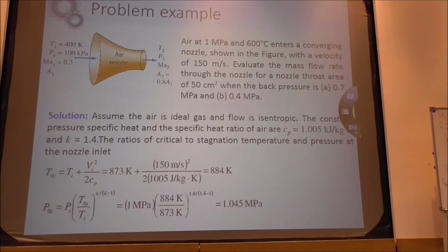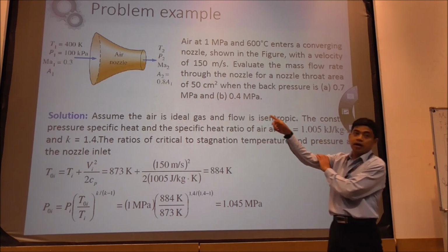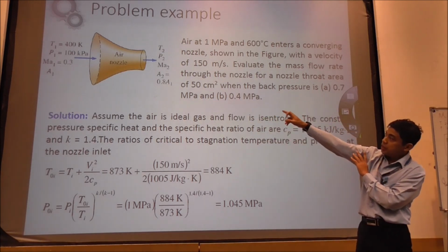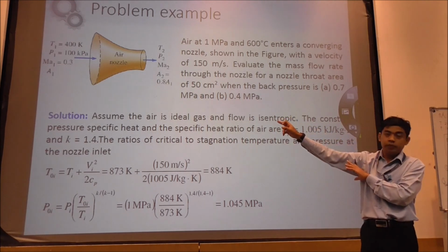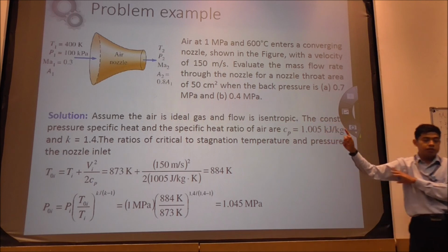Okay, you remember. One more thing. If you are given the equation for the compressible flow, the pressure over here is the absolute pressure. That's why you can calculate rho easily by having P over RT. Rho is P over RT, and then you can use those P right away, because those pressures are the absolute pressure.